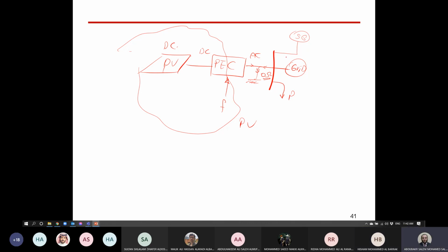Yes. Which means the effect on the synchronous generator will act like a very high load, which means the power consumed from the synchronous generator will be very, very high. This will lead to a sharp decrease in frequency. In this case, the speed governor cannot work properly because the speed governor needs time.